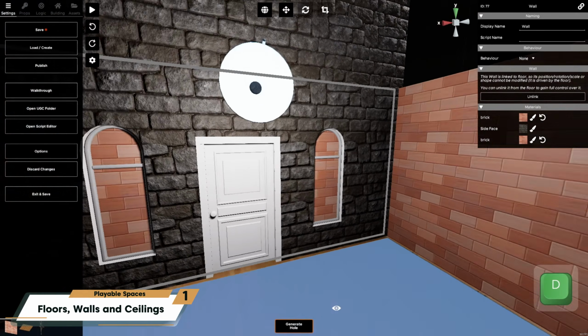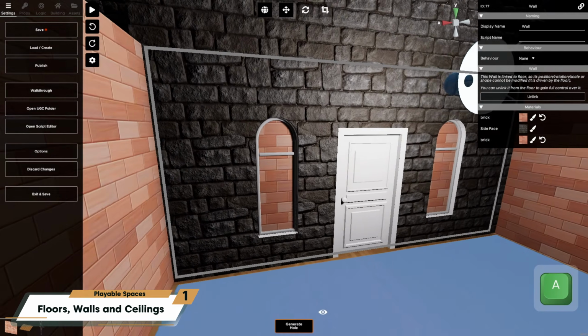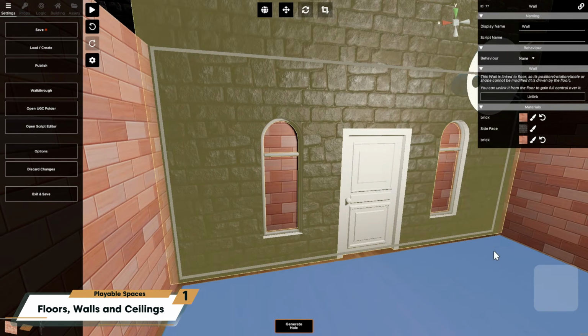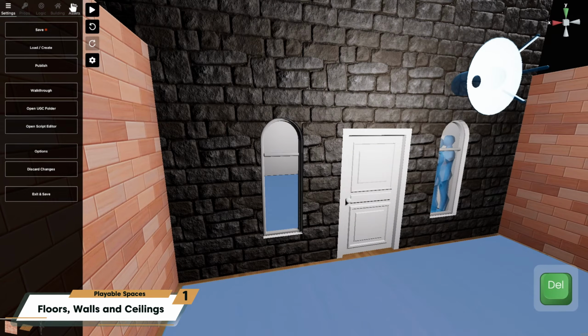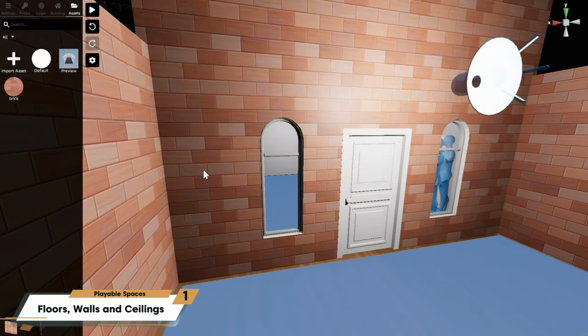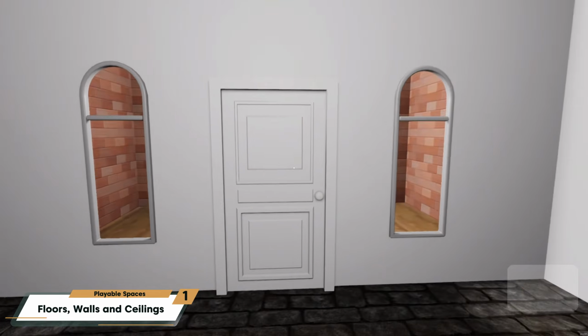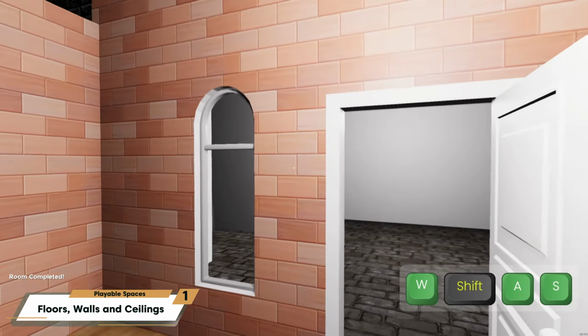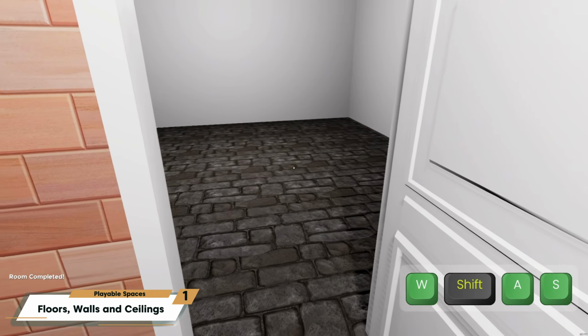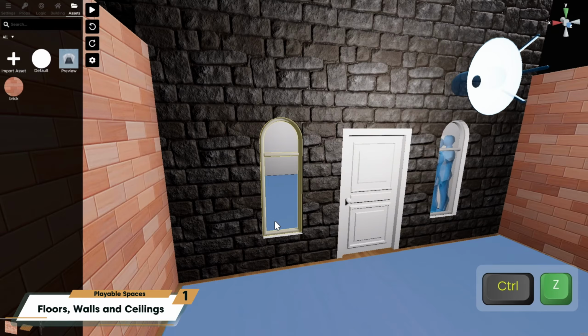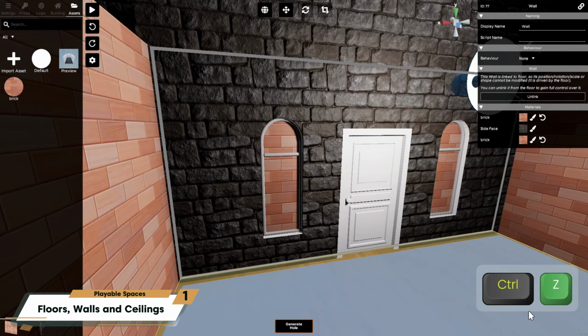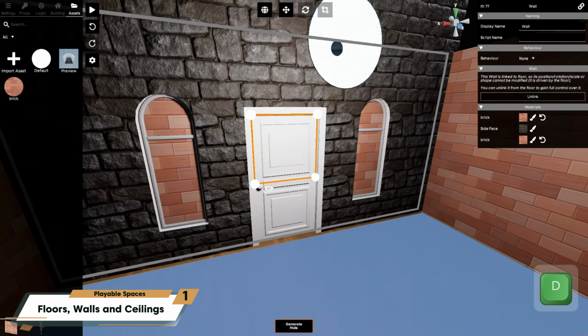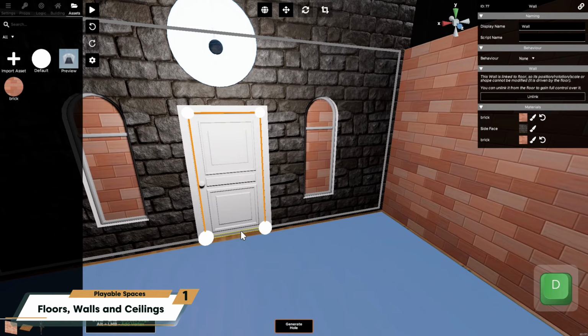So you have a few options here. You can delete that interior wall from room 2 and then, if needed, give the matching wall in room 1 a new material for its back face so it blends seamlessly. For more on materials, see the materials video. Alternatively, you can keep the wall in room 2 and instead create a hole in it in the shape of your door or window. And that brings us to our next section.